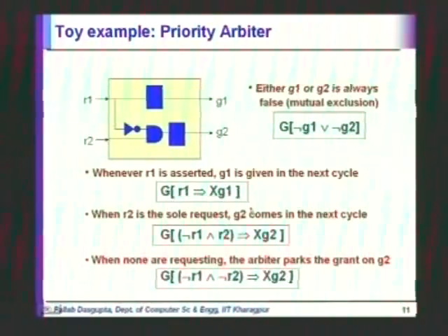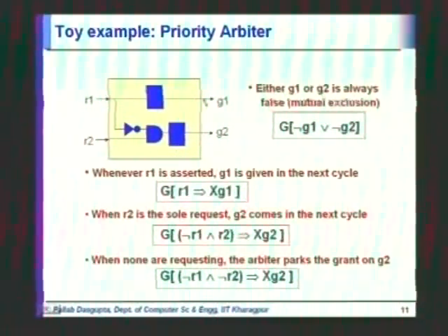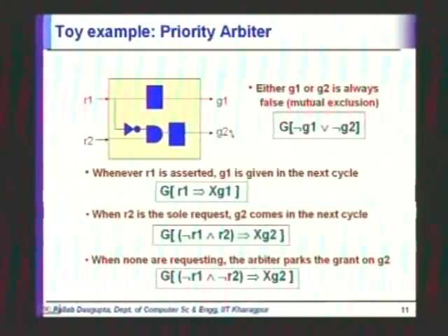the design. So first property is checking whether always not G1 or not G2 will take place. Okay. So to see that, we see that when R1 is high, then in the next cycle G1 will be high, but if G1 is high, then when R1 is high, this one will drive this to 0, so G2 will be low.